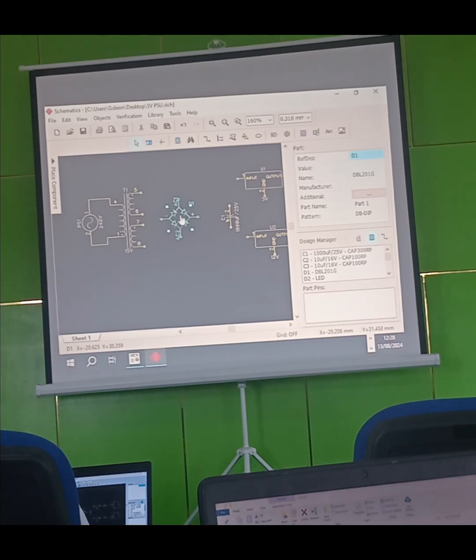So now if you have that 32 going straight into it, and a current of maybe 0.5 amps is running through it. 32, right? And your output voltage is what? 5. 32 minus 5 is 27. 27 multiplied by 0.5. That's the heat this guy will be dissipating.